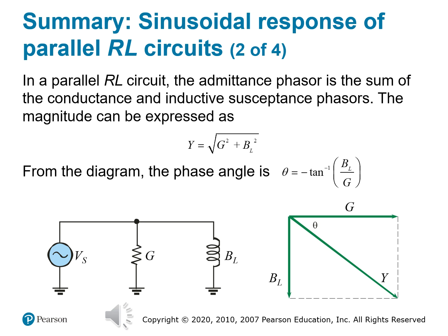You can solve for voltage and current in parallel AC circuits using Ohm's law, but with Y, so where you have I is equal to V times Y. And if you understand how frequency affects current division between resistance and inductance, between R and L, the triangle is essential and it helps you analyze high-speed analog filters, maybe RF tuning networks, and parallel power circuits, to name a few, especially where inductive lag plays a major role.